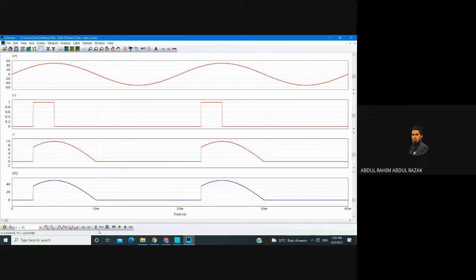Okay, what is behind the picture is that we are trying to understand the non or semi-control device. Semi-control device. This is for a resistive load. But if you use other than this resistive load, let's say impedance, other components of C and L, you can see that there is a tail on the current I, which will not end at zero.